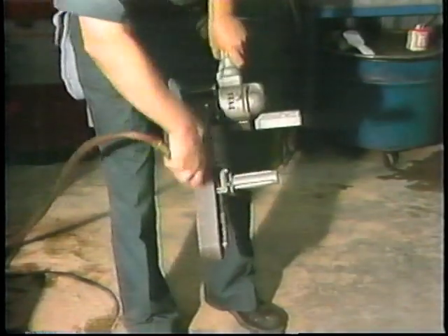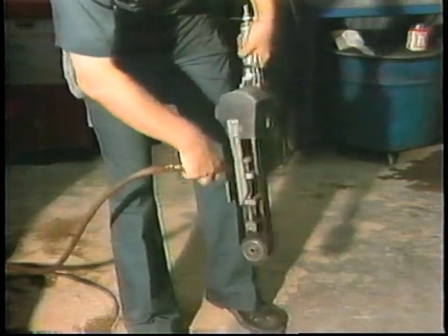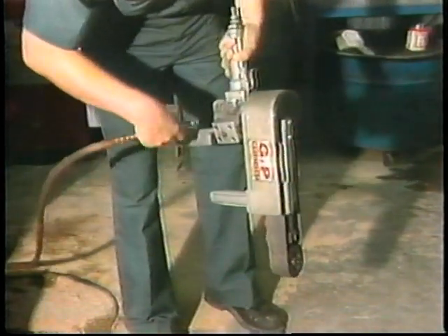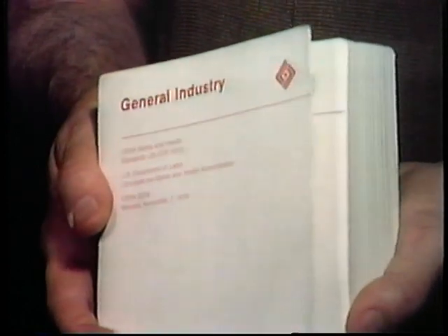Now let's talk about another safety device. This operator is performing a task that's done in many manufacturing plants across the country. He's using compressed air for cleaning. Here's what could happen if a hose broke and the airflow wasn't stopped. It's called whipping. To help prevent this from happening, the OSHA regulations require all hose systems larger than 1/2 inch to be equipped with a safety device that will reduce pressure in the event a hose or fitting should fail. The valves used to do this are called air fuses, or excess flow valves.